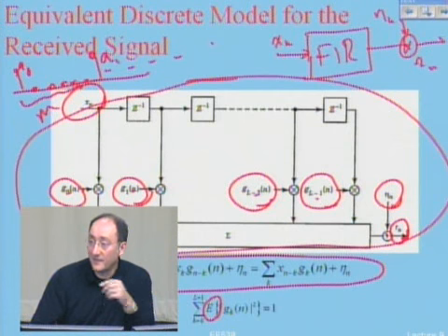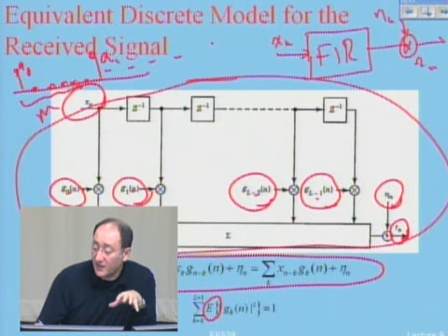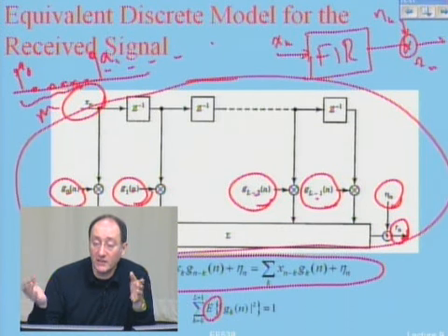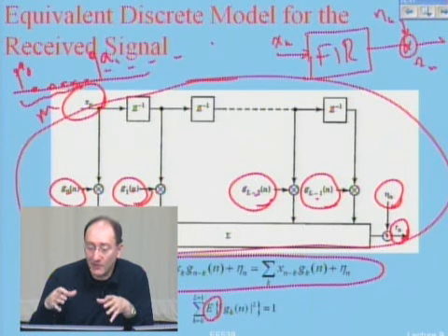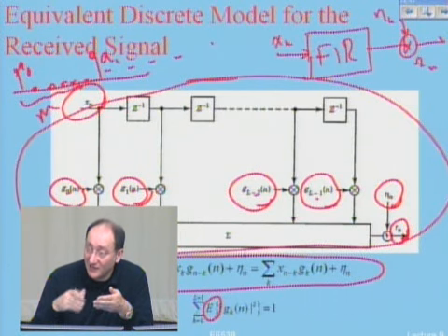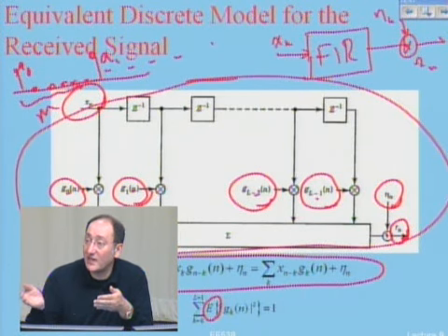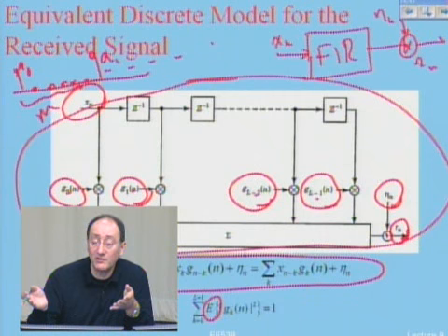Bottom line is that, and this is very good for any type of signal processing, because when I implement the modems, I do sample the same way. I do sample them faster than the T, and I process them like that. Like in voice band modems, for example, the baud rate is 2400, they sample it at 9600.